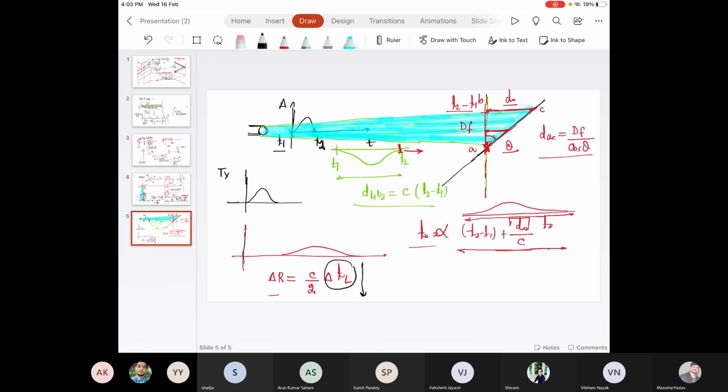Now this is transmitted laser pulse and this is received laser pulse. Time t, this is amplitude transmitted, this is amplitude received. So when this pulse starts to emanate from the transmitter, at which point we generate a signal to the counter to start the counting. Because see, this length is T2 minus T1.